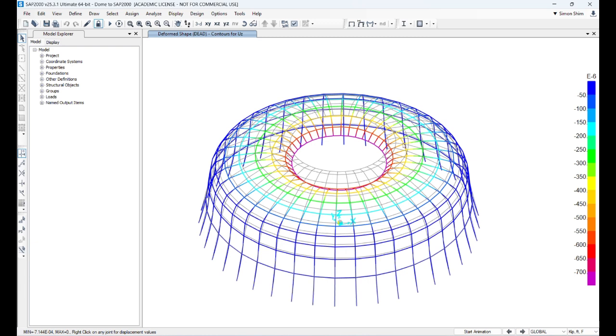All right, I think this model is done. Something I didn't adjust is the shell element, which also has a stiffness, so it shows relatively very stiff. I'll reduce the stiffness of the area elements and show you another model.